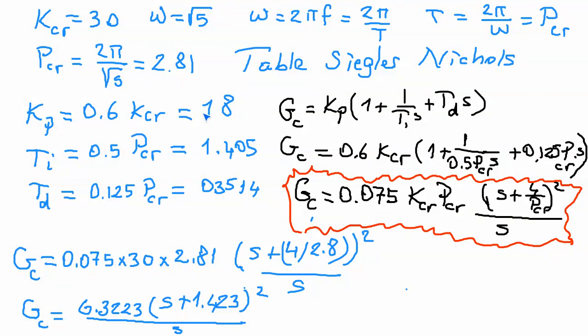So we obtain Kp, Ti, Td. These are equations you don't have to memorize. Either use this one or that one. I prefer that one. So I put this one and I obtain the added value for the controller. We are adding a double zero at 1.4 and 1s. Okay. Up to here, is it all right, kids? Is it alright for you?